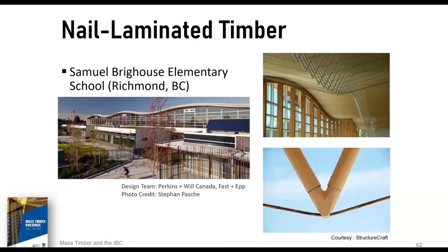The 10,000 square foot undulating roof was constructed of nail laminated lumber and inverted king posts to span the 35-foot wide atrium. The roof was entirely prefabricated in sections in the shop using jigs to simulate the arched support beams. The resulting warped panels, 40 in number, were then coated, trucked to the site, and erected by the crews.